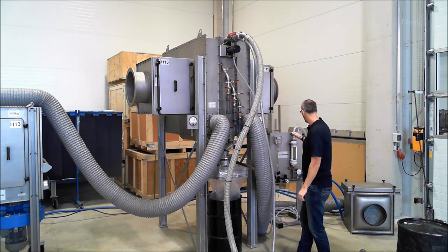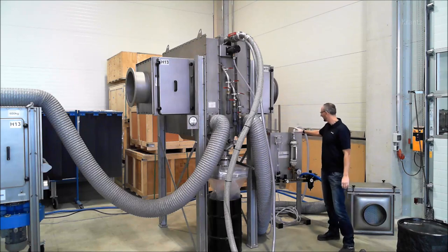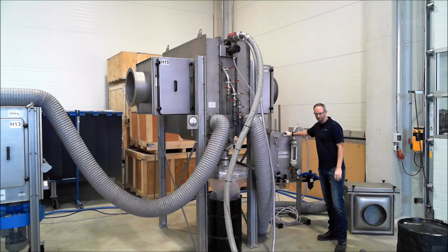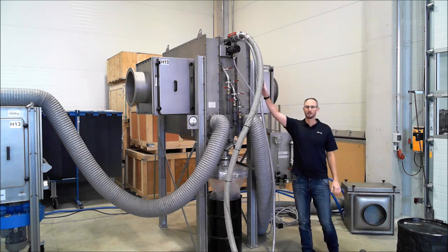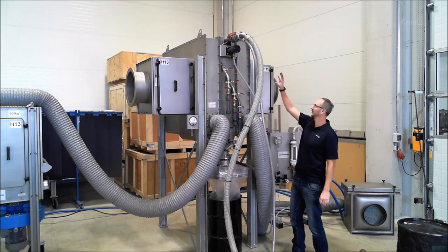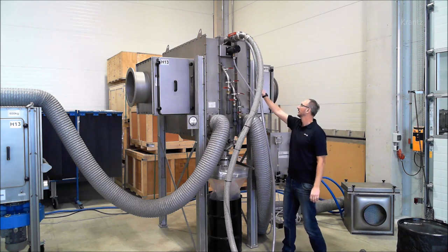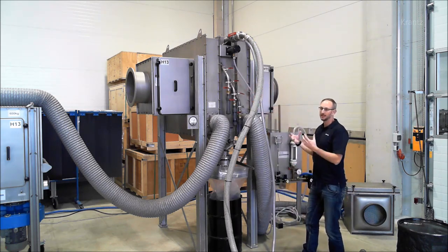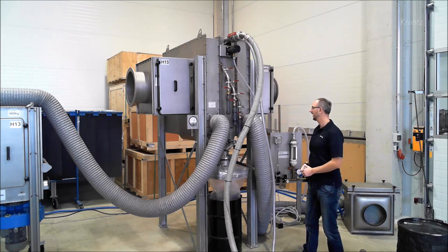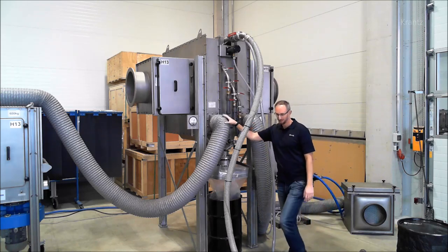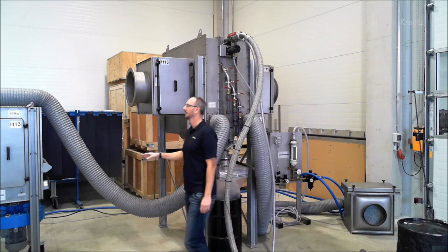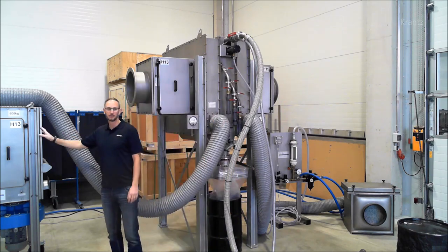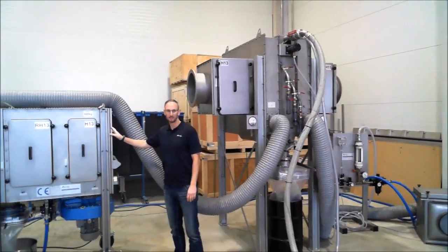Process, we have the filling device itself. So we have here the device to operate the injector, and this is connected to the housing on the top. From here the carbon will be shot into the housing. We have a vibrator unit on the housing so that we can densify the carbon during filling, and then we have an extract here which is going to our re-cleanable HEPA filter, which you can see now.